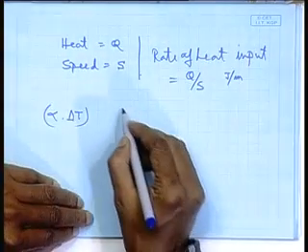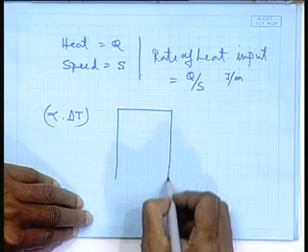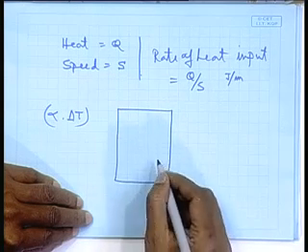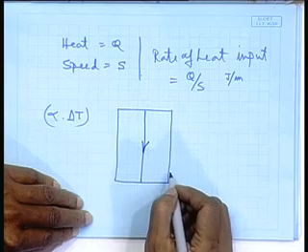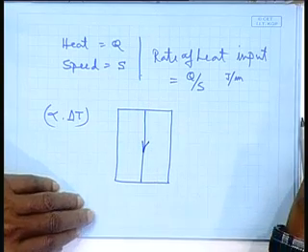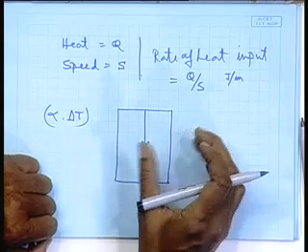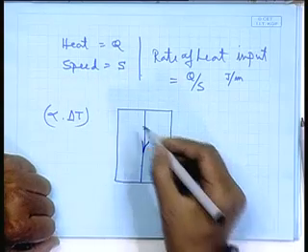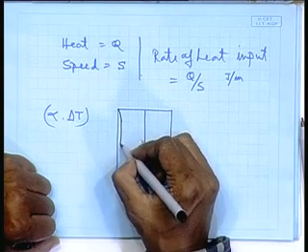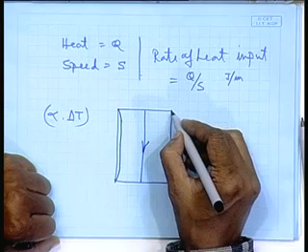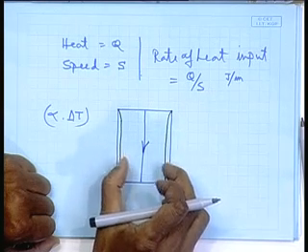That means if the plate was like this, once I heat it along a central line direction, there is a possibility that after it is done, I measure the dimensions of the plate, and I may find that the plate boundary has become like this, it has shrunk.